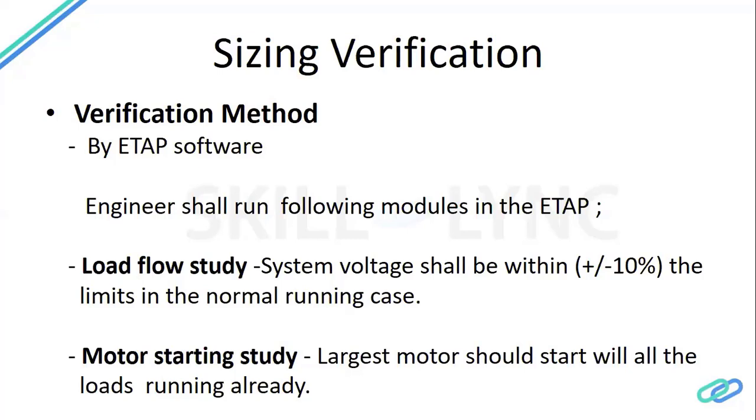Next is the motor starting study. This is a very important study for the transformer size verification, because whenever the motor starts, due to the high starting current, it gives a voltage drop, and if it is beyond the limit, your system may shut down.